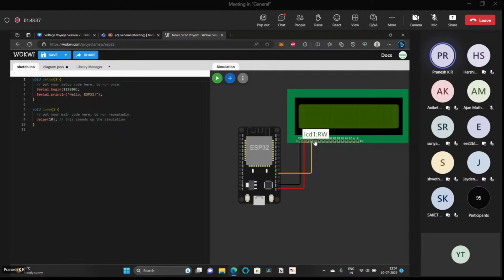Don't ask me why. So we are going to write stuff in it, so we'll connect this to ground, because as I said, write corresponds to 0 and read corresponds to 1. And at the end, we'll play around with these pins. Like we'll put this read write to 1, to power, and we'll check whether it is displaying stuff or not.